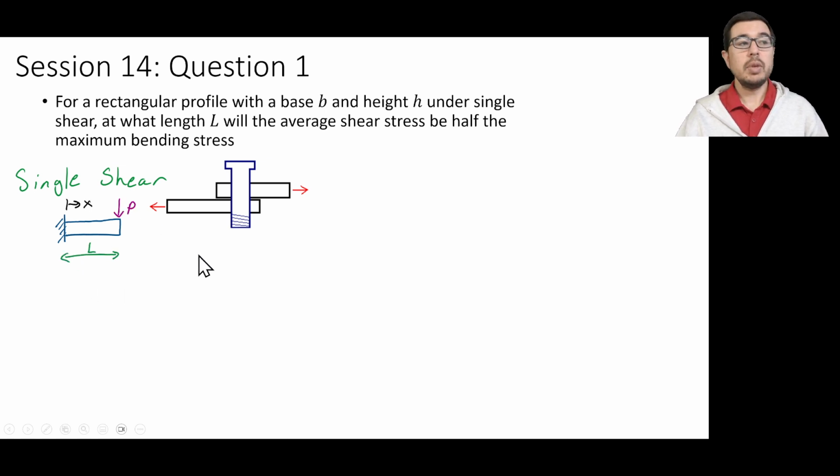Now, this may be a little bit of a stretch, but imagine that this wall is this portion right here that's being constrained by this plate acting on this portion of the pin. And then this is going downward with P being this force, and it's pulling it in this direction like you see here. We've chosen this model for beam bending instead of a wall-wall type configuration because it is a determinate system that we only need to describe through equilibrium.